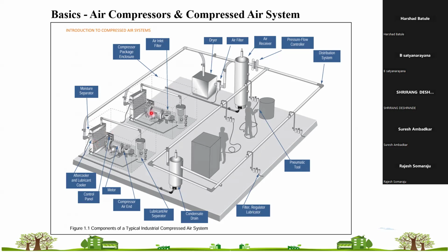So you need to put your smaller compressor on load unload cycle, because in a screw compressor or any compressor, the unload cycle also has energy consumption. You are not delivering any air, but you are consuming energy. In unload cycles, almost 30% of the energy is consumed.